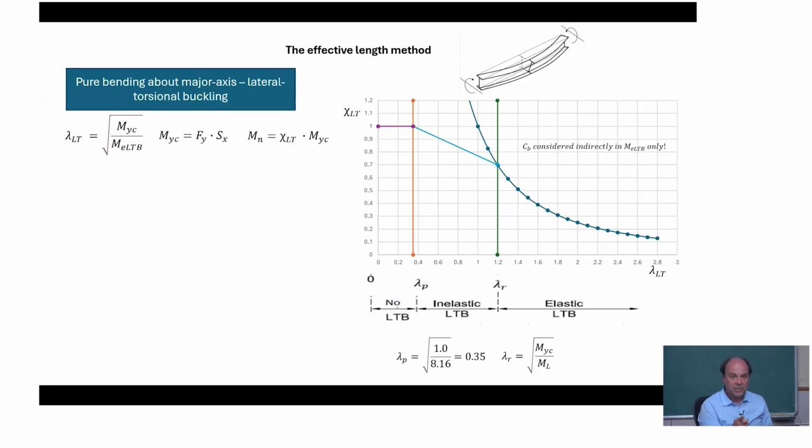It's also important that such modifications exist also in the Eurocode and therefore, I guess, also in the Indian standard. It's not as relevant as in the AISC, but it's called a small f, I think. So the effect of the stress distribution has a direct, beneficial effect on the strength, but by far less important than in AISC. Okay, so in this example we will do nothing more.